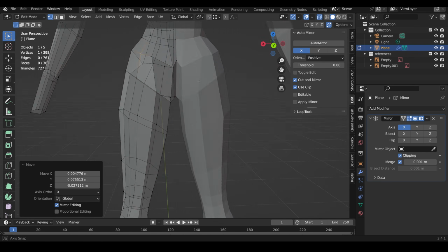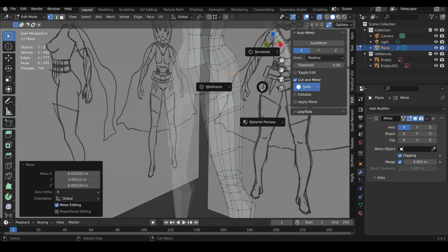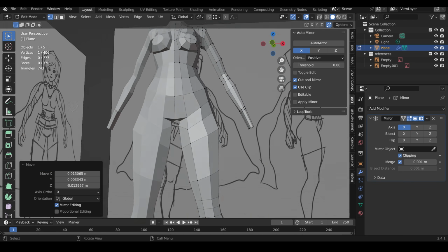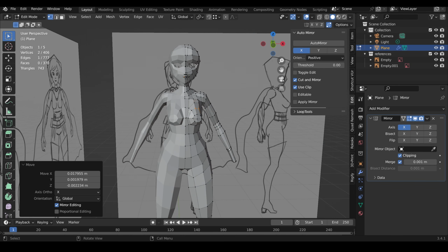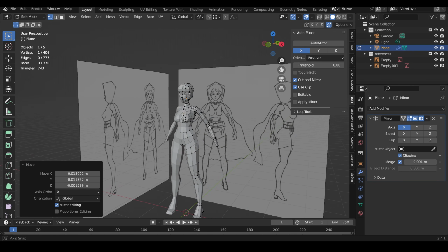The buttocks are another tough area, and again, they're similar to the breasts in the sense they're rounded and you're trying to work with a small amount of polygons to get a rounded shape. Usually you need to just add a loop cut underneath the buttocks to kind of create that crease at the base of the bum, or the bottom of the bottom, you could say. And then we have a reasonably okay looking body.